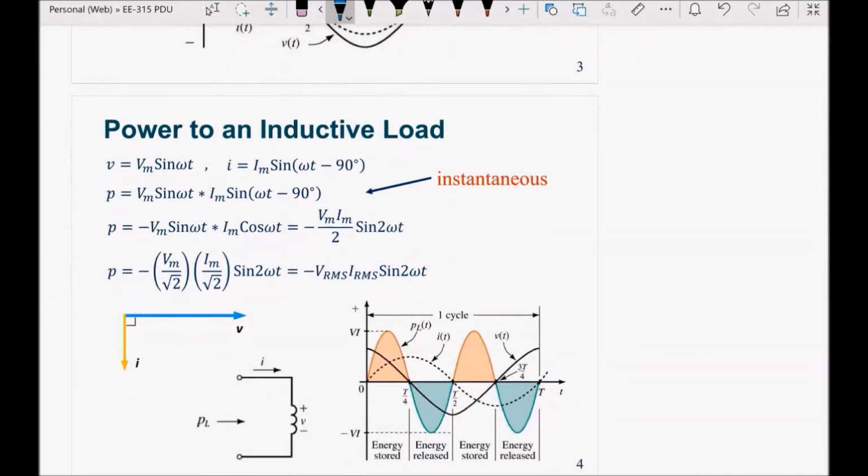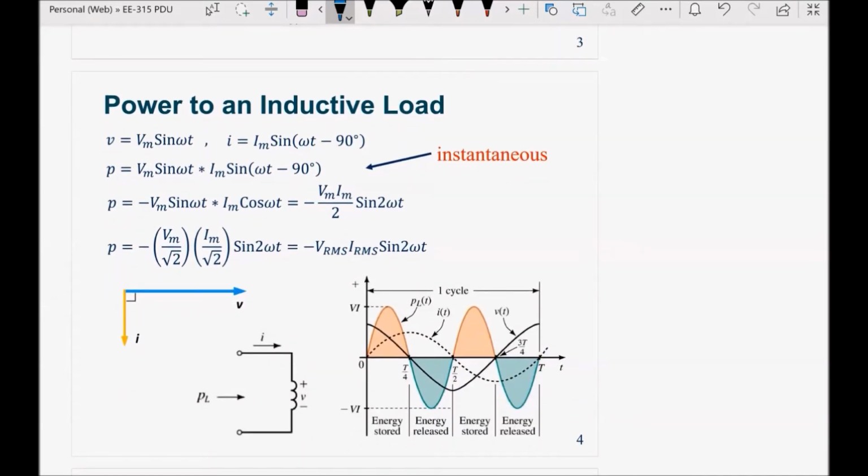Moving on, let's talk about an AC circuit with an inductor connected across a supply. We know that the AC supply is Vm sin omega t, and the energy flowing in the circuit will be stored in the inductor in the form of a magnetic field, which is also going to oppose any sudden changes in the rate of flow of current. To derive the current, let's say the induced EMF is L dI by dt. We are all familiar with this.